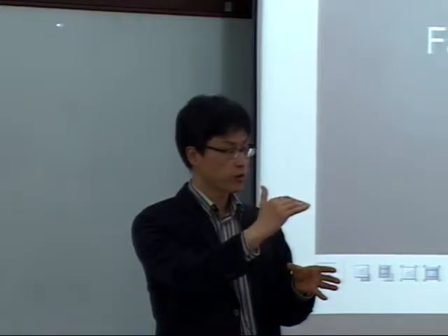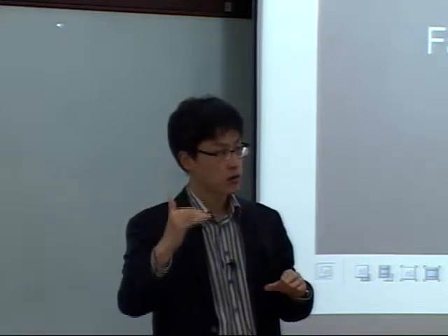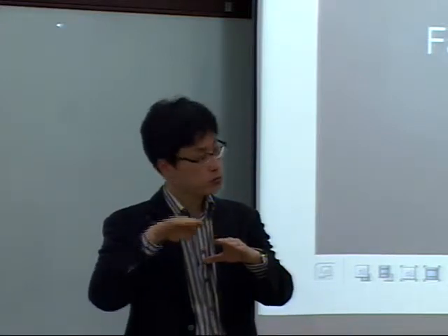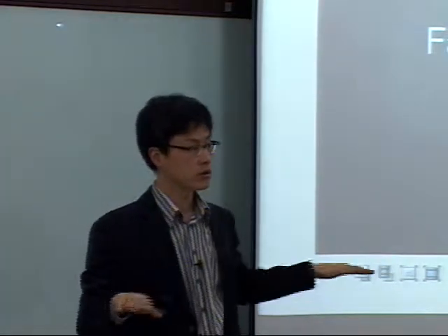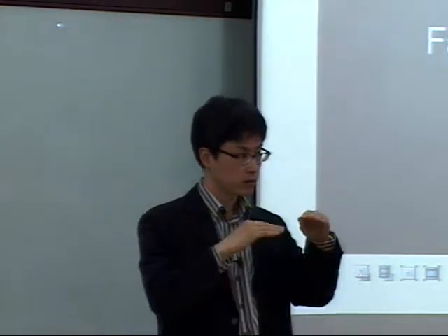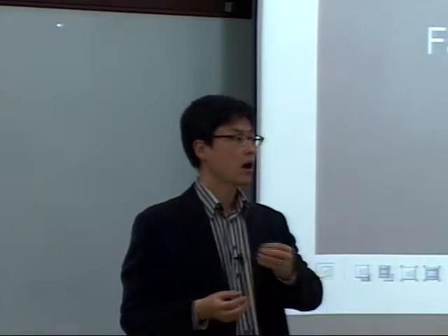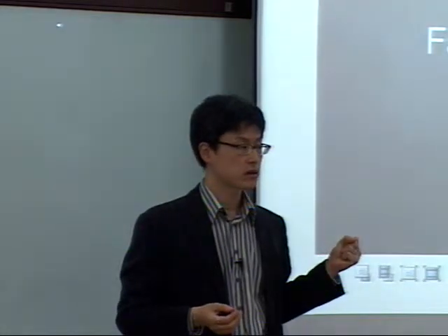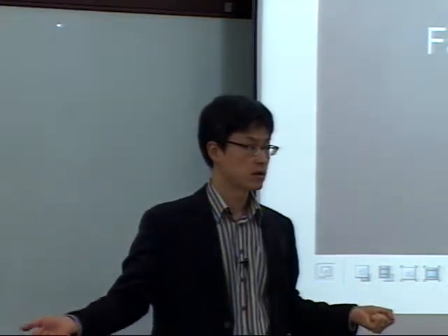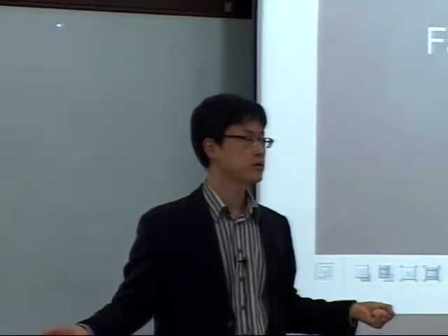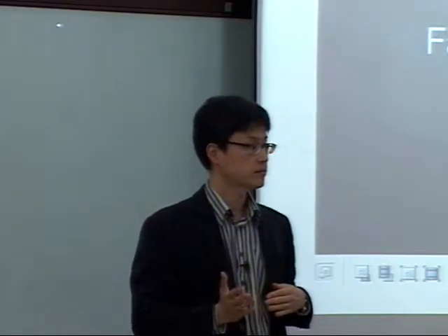And when you solve some problem and reduce the cycle time, a new Herbie appears. If you reduce the cycle time again, a new Herbie appears, and eventually all the workstations' cycle times will be balanced. And then every process is now the constraint, which is a symptom of a just-in-time production system. Their cycle time is now the takt time.